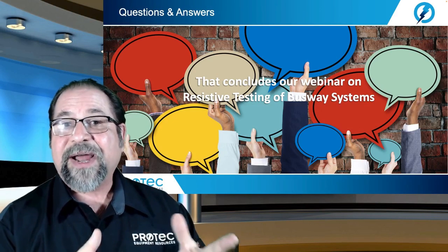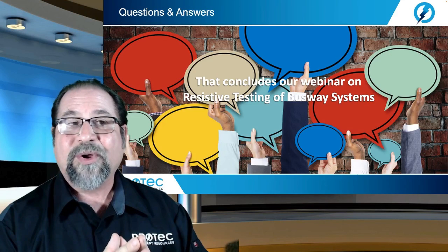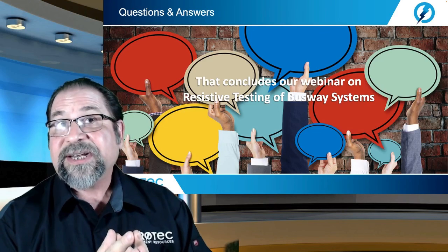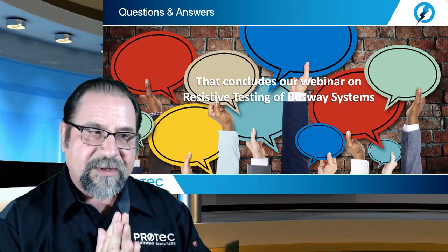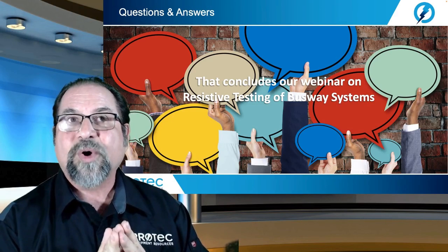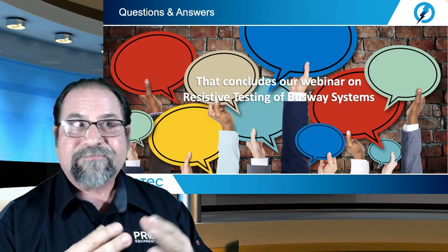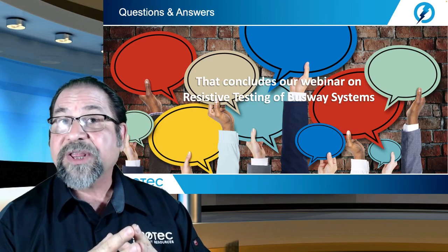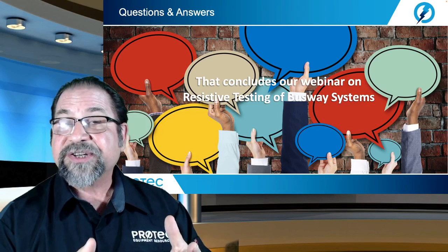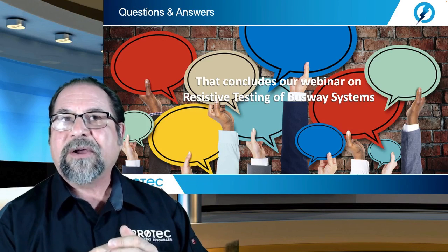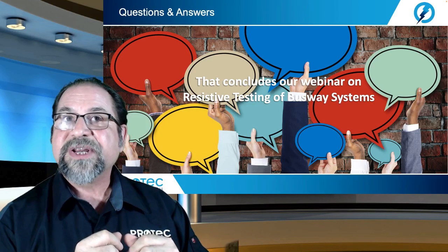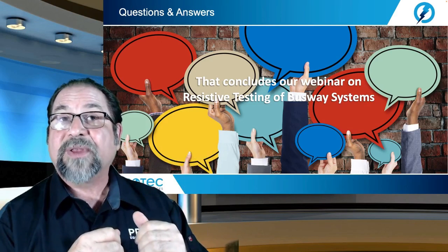I was kind of inspired to do this particular webinar based on my days reviewing data sheets during various service jobs for the service company that I was working for. And all too many times, one of the common mistakes that were made was simply going out there, taking insulation resistance measurements, documenting on the spreadsheet, but never properly using the NETA tables and correcting the measurements for length.